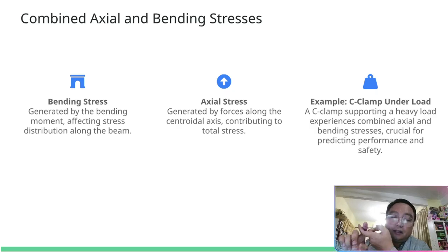So naturally, the shape that makes it a hook is more strong. So rarely can we see a hook be broken. But of course, upon prolonged usage, it may break. It is a natural thing. When you can see with your eye the traces of fatigue, cracks and everything, better you change to a new one.